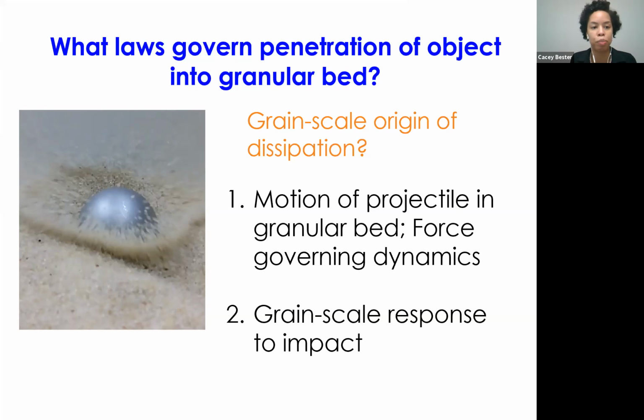First, I'll talk a bit about just the motion of a projectile in a granular bed, and we'll use those experiments to find position measurements that we can then use to develop an empirical force law. And then to better understand the drag forces that act on an object as it penetrates the granular media, I'll show you all a few experiments in which we use photoelasticity to get a sense of the grain scale response to impact.